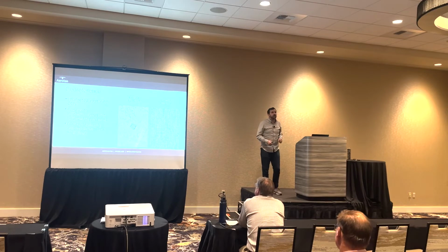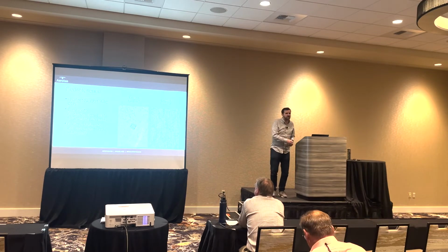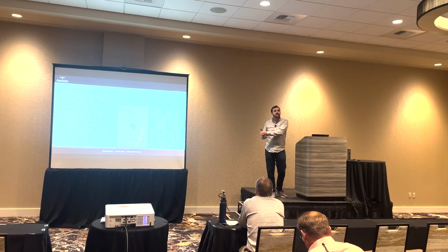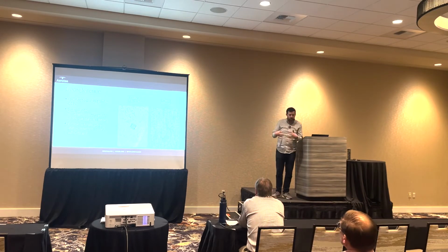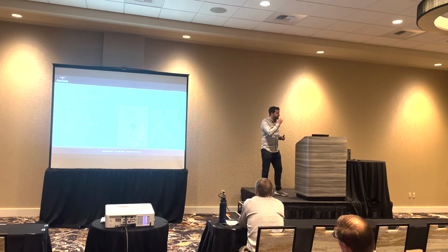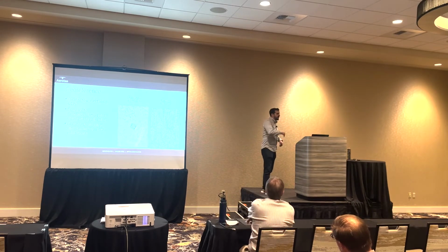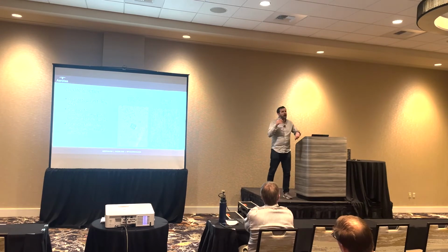At the early stages, we don't actually care too much about accuracy. In the early stages of processing, we care about precision. And that RTK is very, very precise, especially because when you're using a local base, your baseline distance is so short that the precision is great. And the way that we get accuracy is by georeferencing it to ground control points.